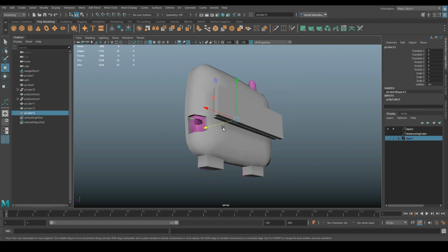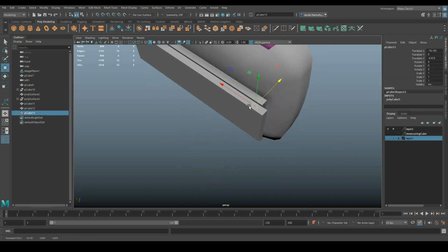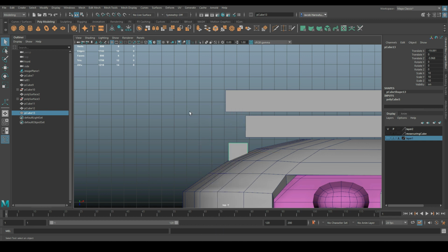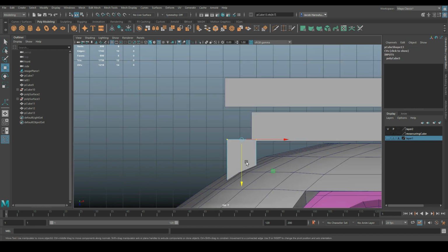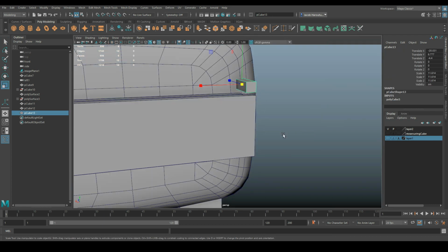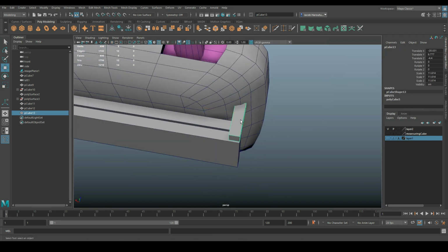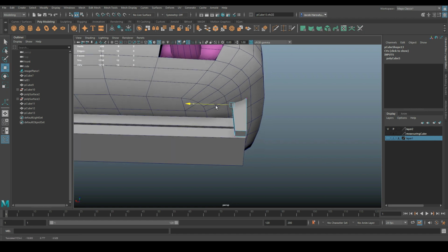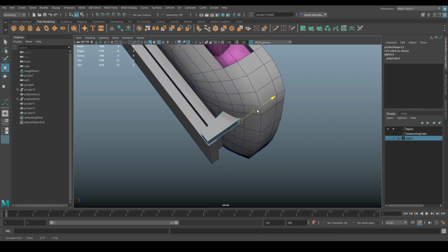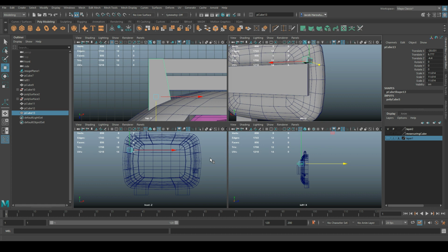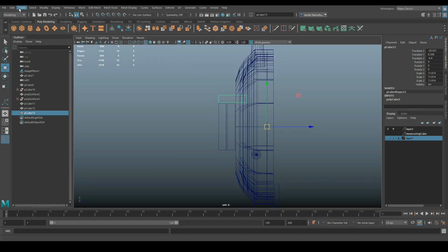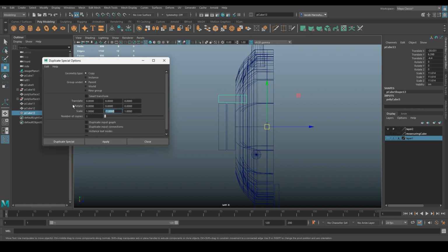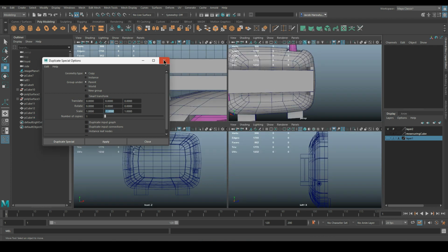All right, and to create the pivoting areas, I'm gonna have to create a point where they meet and about the same size. And this is gonna wanna meet that top one there, okay? This is where the hinge is gonna be. So we're gonna wanna make sure that this is nice and supportive. I'm gonna extend this out just a little bit, likewise with this one, and bring this a little closer. And I'm just gonna duplicate special in the Y-axis so that this has a pivot.